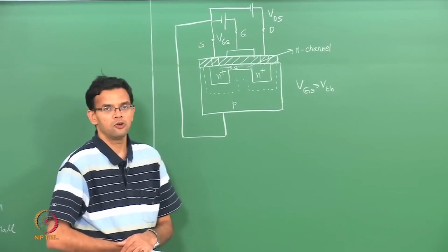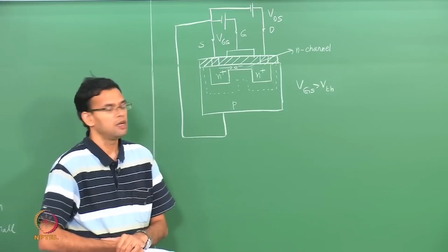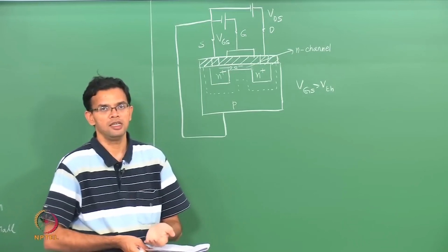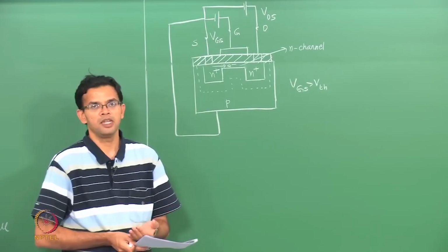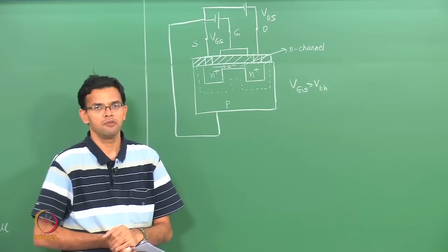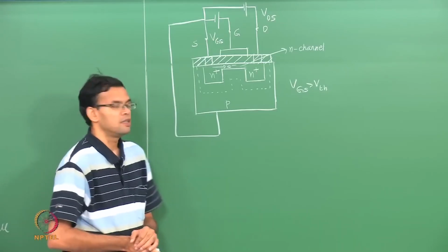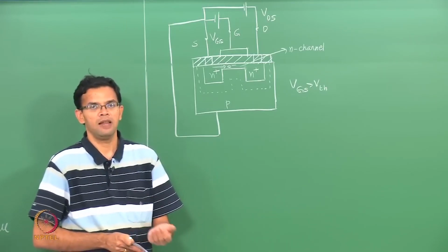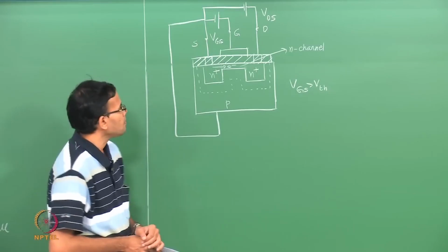Thus, the gate source voltage essentially acts as a controlling parameter to control the current in the MOSFET, and this is the transistor action, where the voltage between two terminals determines the current or the voltage between other two terminals. You can also say that this gate source voltage acts as a switch, so it helps to turn off or turn on your transistor.